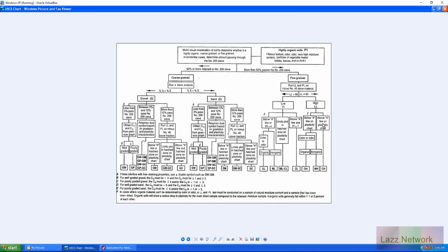It's only then that they would care about doing the full suite of testing, where it would fall somewhere in between here. But most of the time, if it's for new construction, they only want to use suitable materials. If they see peat, it's just an automatic, okay, it's got to get removed, you know. Usually removal is what they typically do.